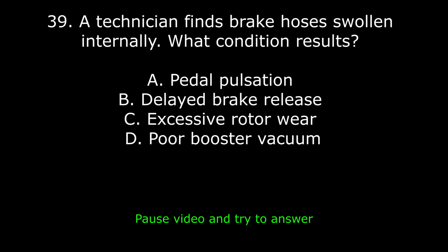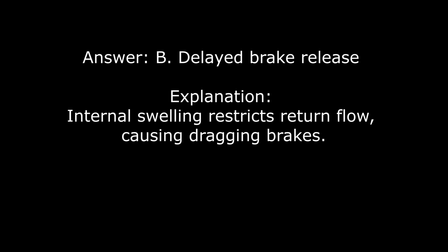39. A technician finds brake hoses swollen internally. What condition results? A. Pedal pulsation. B. Delayed brake release. C. Excessive rotor wear. D. Poor booster vacuum. Answer is B. Delayed brake release. Explanation: internal swelling restricts return flow, causing dragging brakes.